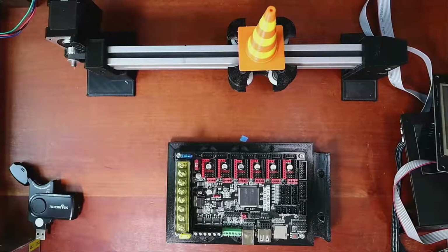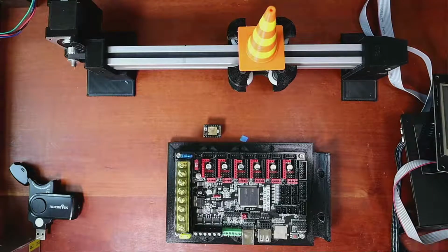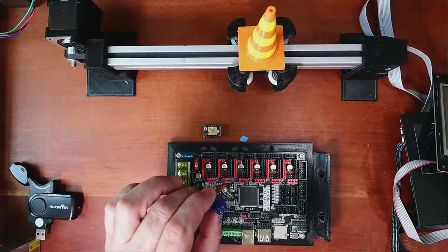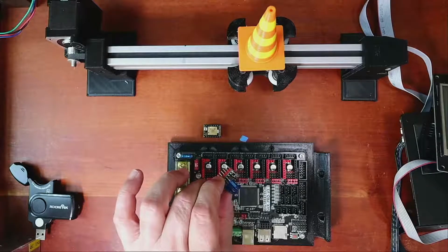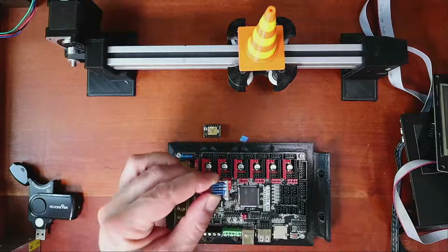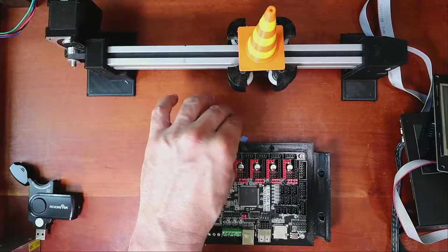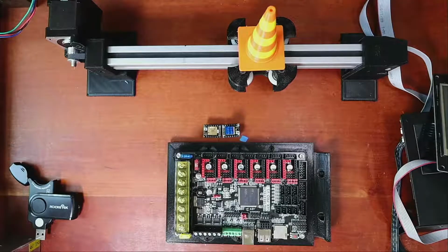This is the TMC2208. With the TMC2208, it does basically controlled stepping, so that you do it via current in the advanced configuration. Then there's a TMC2209. This one is slightly different. It has what's known as a sense pin on it, so that if you reach the end of an axis, you don't need to use an end stop. You can actually set the sensitivity for that.